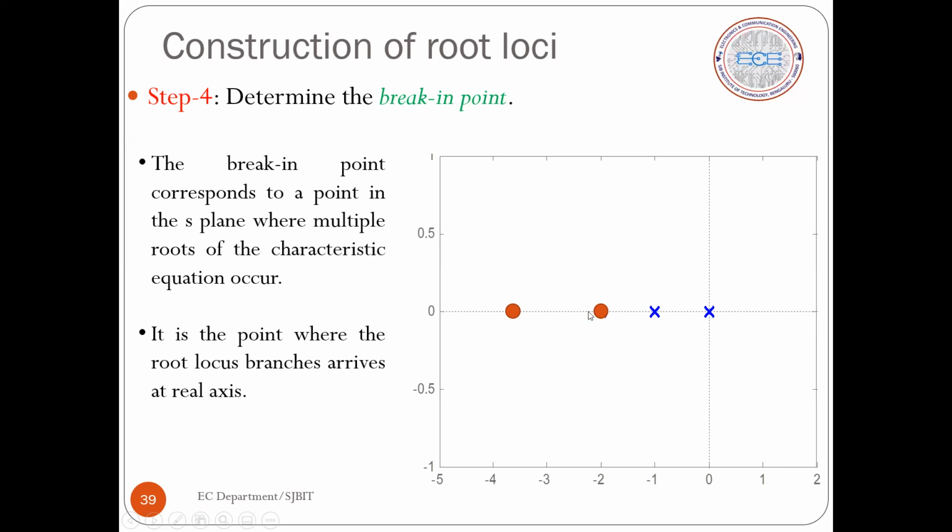Okay. So now we will see whether root locus exists between these two zeros or not. Take any point P and try to calculate the angle condition, and it matches. Angle condition matches. So any point in this section exists in the root locus, since the angle condition is matching. So we say that there exists a root locus between these two zeros.